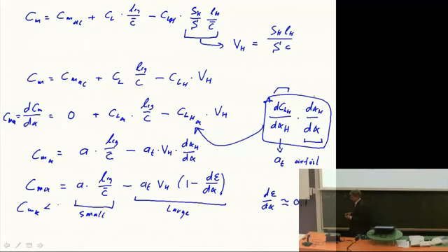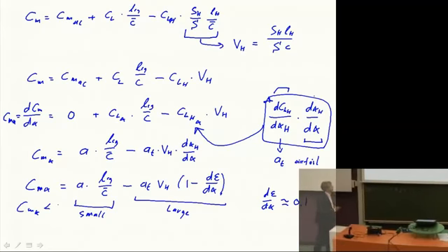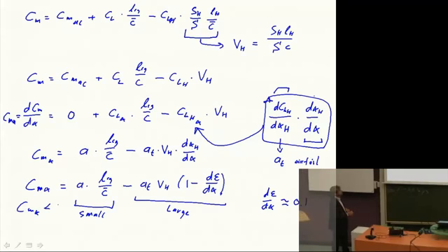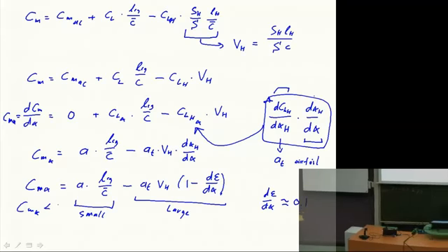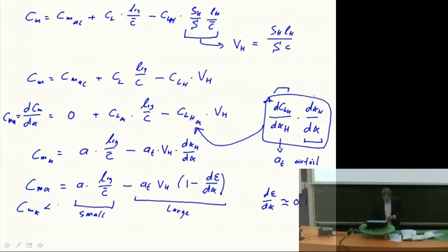And the first part is also the part that generates the lift for our aircraft. Look, it's the change of lift as a result of angle of attack. So the performance guys will say, no, I want this to be big, not small. And then the stability guy goes, no, you should keep it really small, make a huge tail, it will be much stabler. Yes, sure, but we also want performance. So that's again balancing two properties. In other words, if we look at the borderline case, it's just neutral points, you could say. If we look at neutral stability, we could say CM alpha is 0.